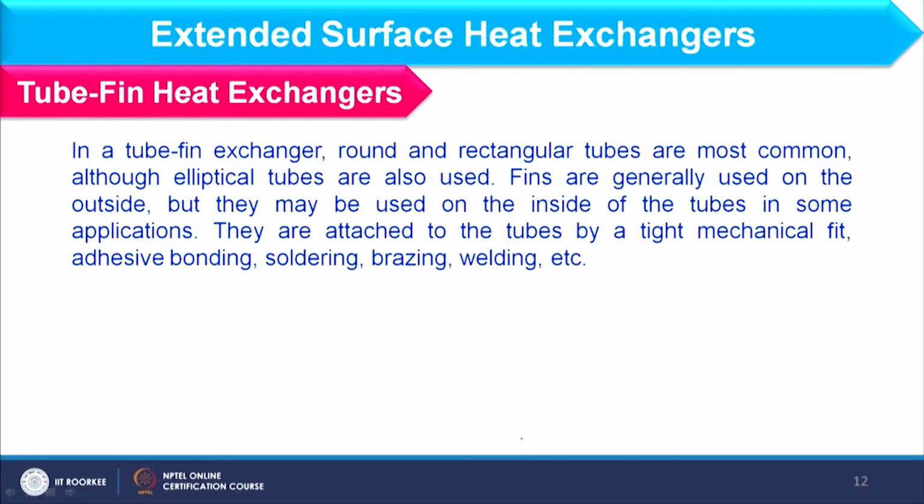Okay, so because of that we are using plate fin heat exchangers, and tube fin heat exchangers we also use, and in these types of heat exchangers round and rectangular tubes are most common, and sometimes we also use elliptical tubes. Okay, and fins are generally used on the outside.